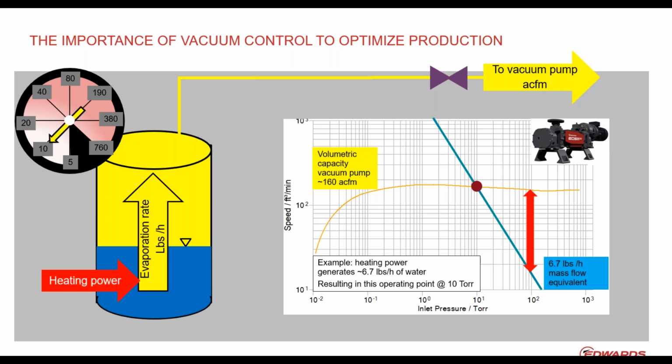But the point is, in a batch distillation or in a batch dryer, you basically come from atmospheric conditions, and then you distill the first light boiling fraction off. Let's say the temperature of your liquid in the reactor determines the pressure. That is the best achievable pressure that you can get, maybe 100 torr.